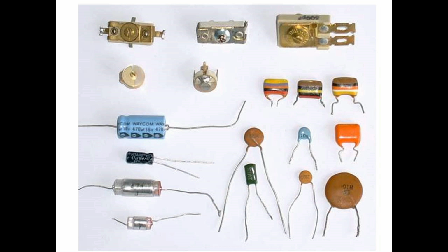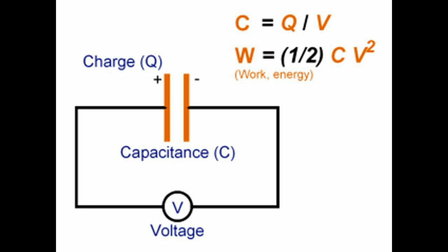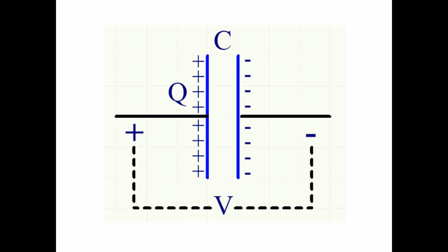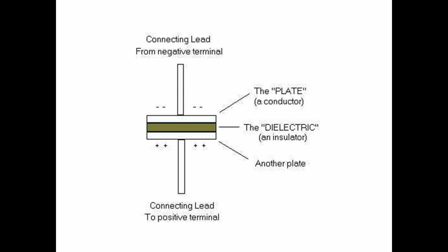Capacitors are electronic components that can be found in everyday devices. A capacitor stores electrical energy through the potential difference between two plates. Capacitors are used to smooth out ripples from AC to DC rectification, or can be used to store large amounts of electrical energy to allow large current peaks with a lower current supply. When an electrical supply is connected to the two plates, electrons move from one plate to the other. This makes a potential difference that can be released rapidly when discharged. Most capacitors use a dielectric material to increase the capacitance between the two plates.